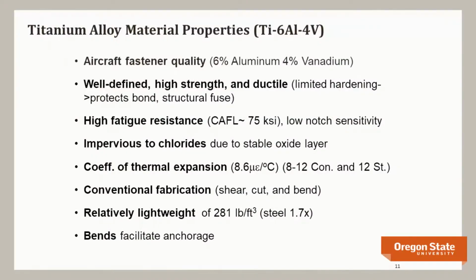I always like to say when the world turns to dust, there will be these gleaming titanium bars shining in the sunlight with the cockroaches dancing on them. And the reason it doesn't care about chlorides is it forms a very stable oxide layer almost immediately. Coefficient of thermal expansion is actually better aligned to concrete than steel, and so we don't expect any thermal incompatibility or thermal stresses because of the coefficients.